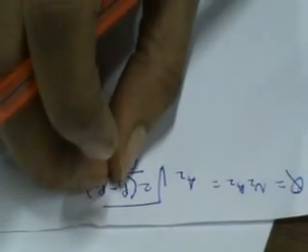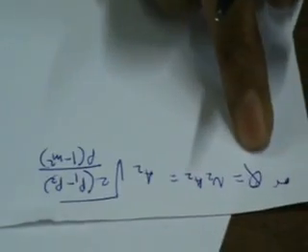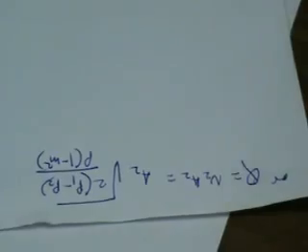That means if you know the area ratio and if you measure the pressure drop, then obviously we will be able to find out what the flow rate is.